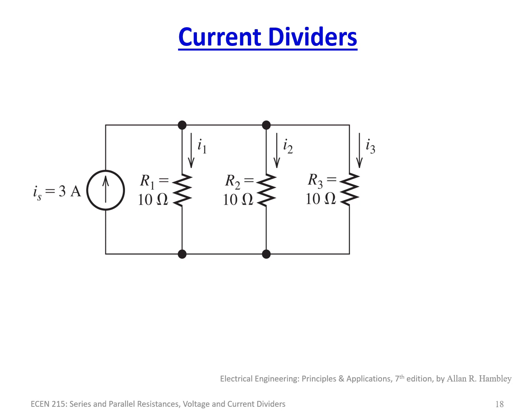I'll let you work out the math on this, but the simple thing is if you have X number of resistors and they all happen to be the exact same resistance value, the easy way to do this is just to divide by the number of resistors. So in this case, I have 3 10 ohm resistors. The equivalent resistance is 10 divided by 3. So our equivalent resistance is equal to 3 1/3 ohms.